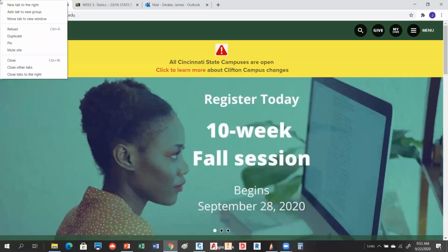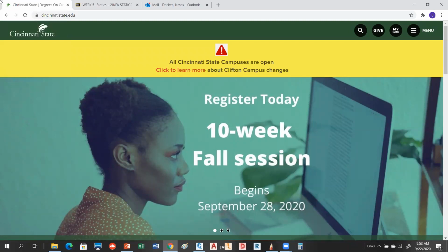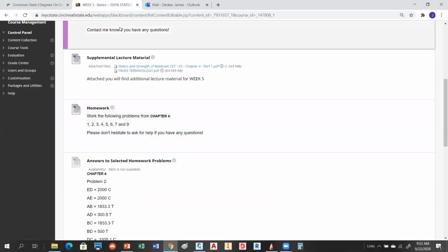Let's look at problem 2. Problem 2 is a little bit more involved, okay? But it's actually a pretty good one. You can start at joint E for problem 2 and then work into A. If you try to start at A on that problem, you're going to have too many unknowns, okay?